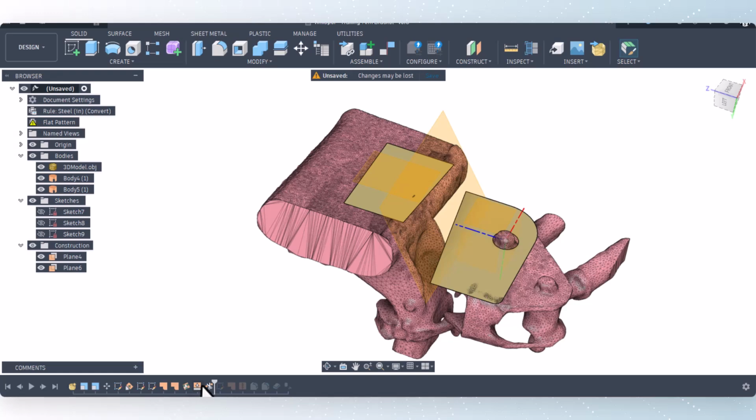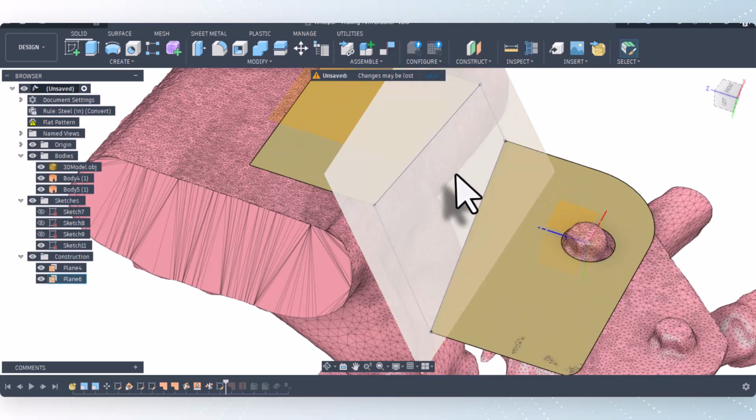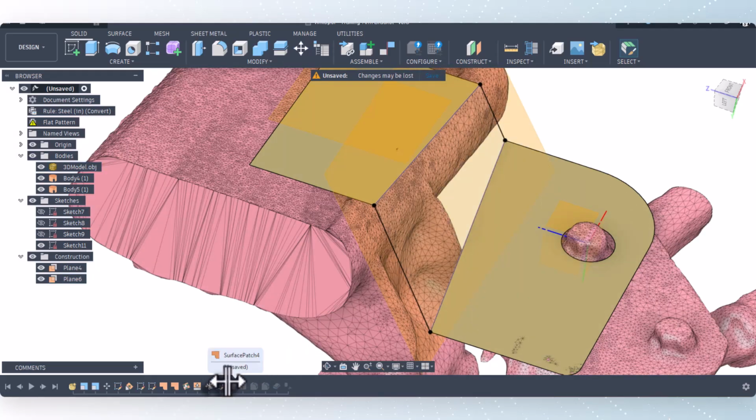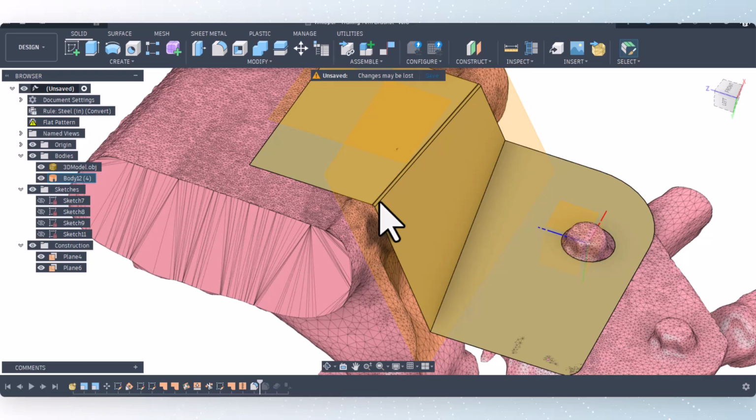And so then I created a sketch on this plane, and I connected together these points. And so the key is, see, this is all planar. It has to be on a plane, not twisted. If it's twisted, sheet metal won't unfold it. And then I created a surface on that plane. Let's hide the sketch. Stitch those 3 planar surfaces together. Put in the inside bend radius, so that's usually the thickness of the material. This will be an outside bend, so that would be twice the thickness of the material.